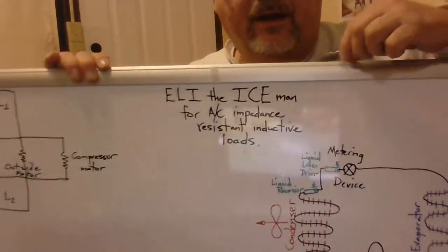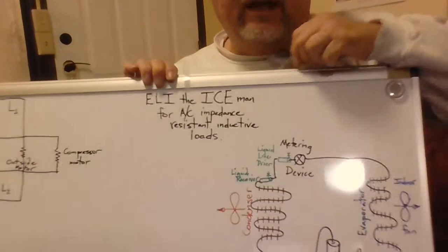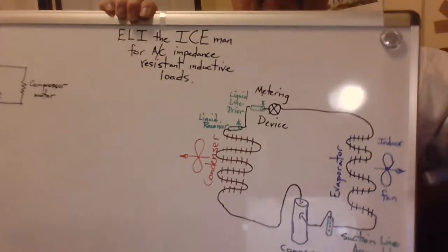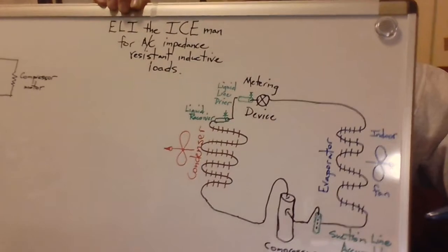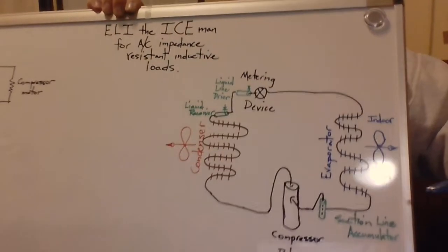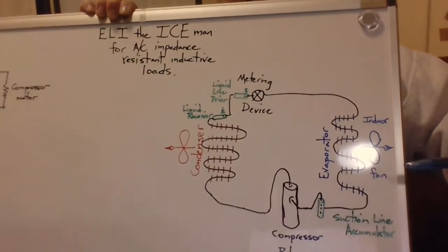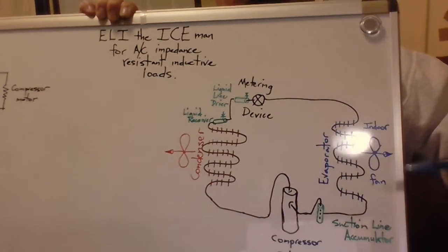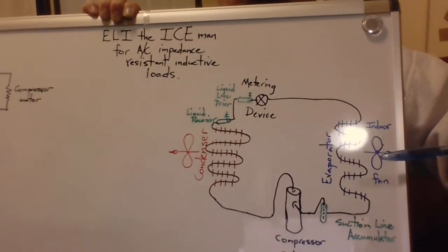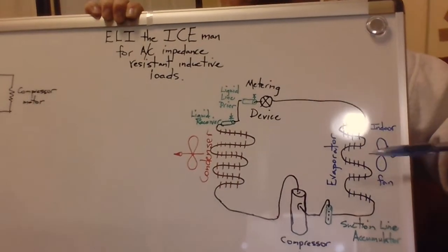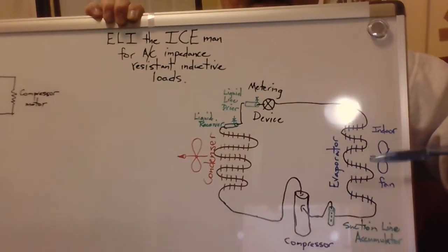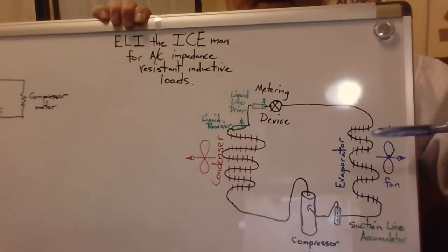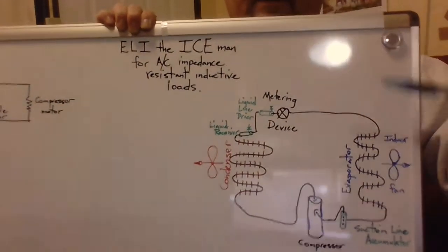And then the third thing will be the refrigerant cycle itself, where I show very fundamental components that are used in both AC and refrigeration. Very important issues of how to establish subcooling, superheat, and what those things mean in terms of blockages in the system, dirty coils, etc., etc.